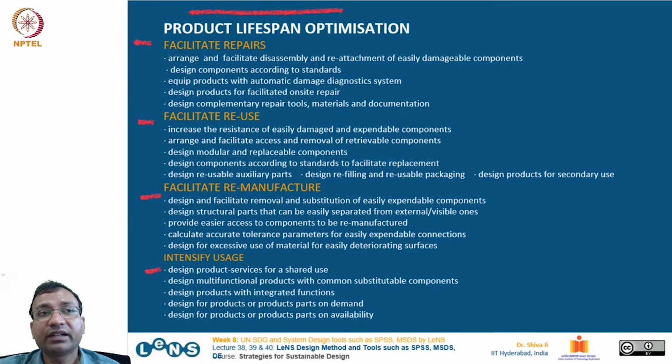Arrange and facilitate disassembly and reattachment of easily damageable components. Design components according to standards so that they can fit from one product to another. Equip products with automatic damage diagnostic systems. Design products for facilitated on-site repairs so that they need not be taken to the service centers. Design complementary repair tools, materials and documentation.